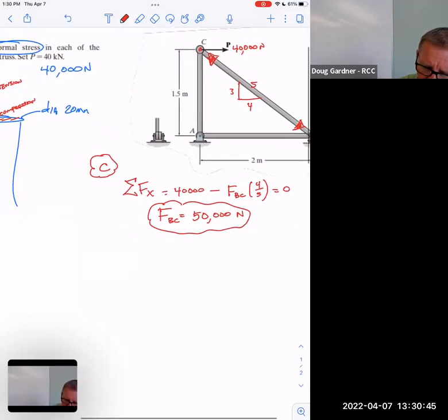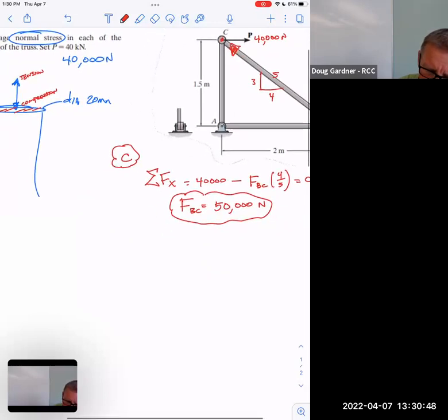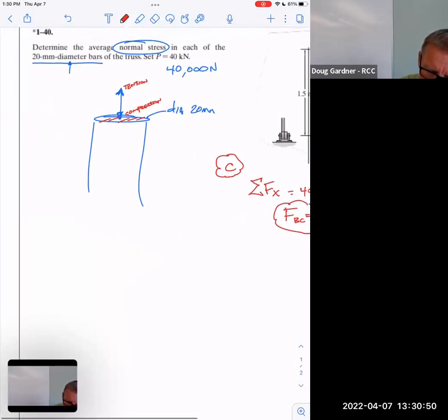They told us. Now let's do something here. We're talking about the area of a circle. Area of a circle is equal to pi times the radius squared. As a time saver, do you agree that radius is diameter cut in half? Now what you could do is say, oh, 20 millimeter diameter, that's 10 millimeter radius, and I'll throw 10 in there. Absolutely nothing wrong with that. But if I replace radius with d divided by 2 and square that, does it make sense? That turns into pi times d squared over 4.